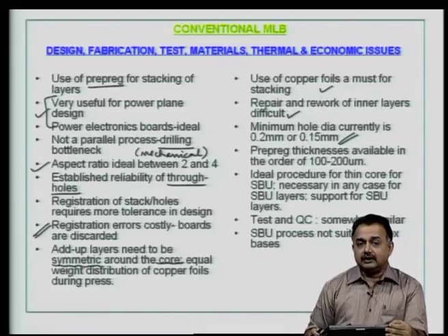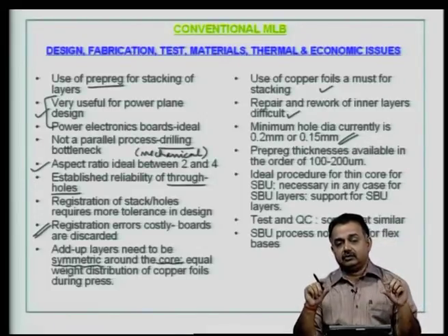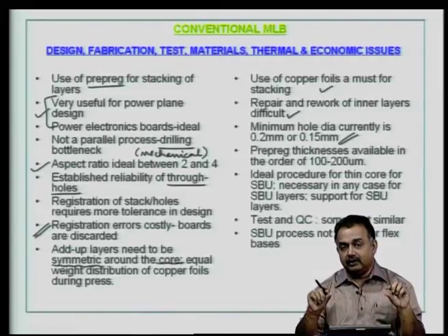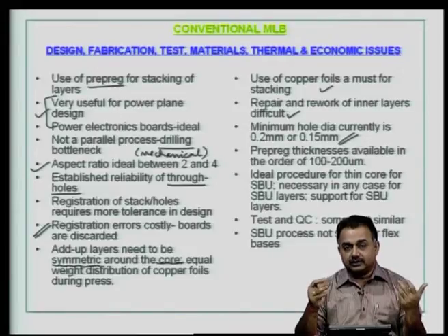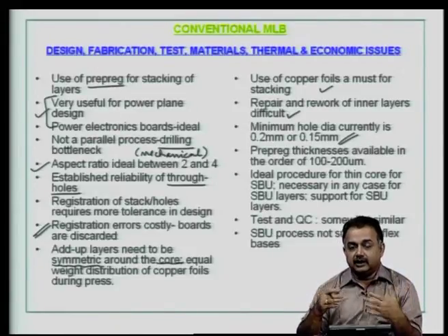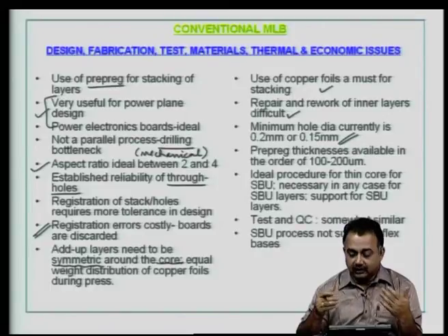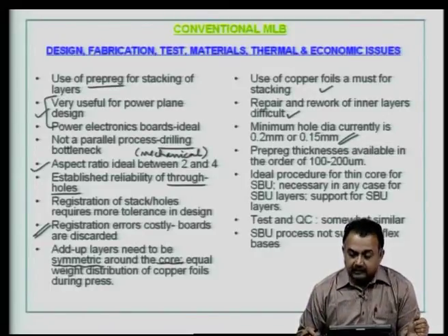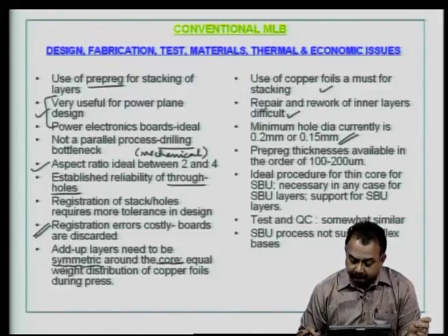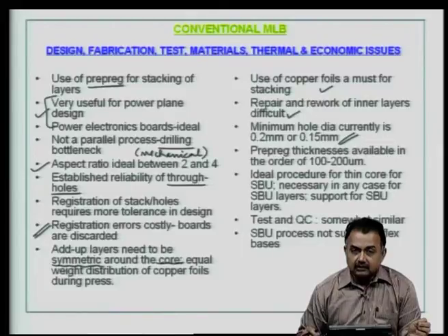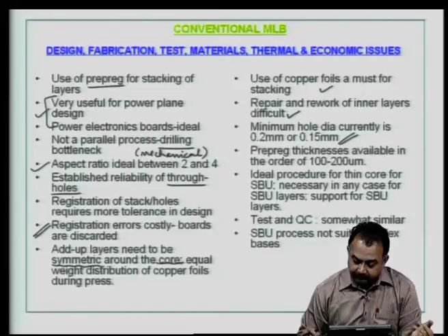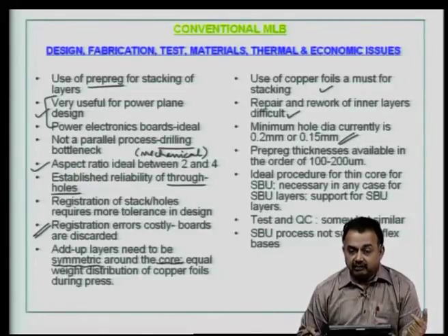So, you can use a conventional board technique for preparing the first 2 layers of your SBU board. If you recollect, SBU circuits can be built up from a core structure, but the essential requirement is that you need to build a thin core using a conventional technique, which is a support for SBU layers. Test and quality control is somewhat similar between all the board processes that we have seen. SBU process is not suited for flex bases.